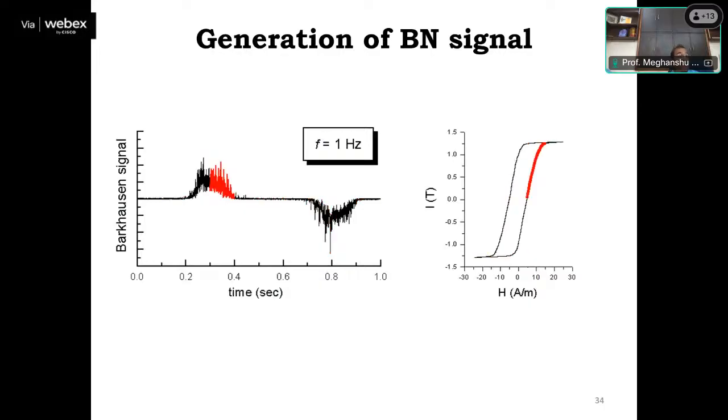This is very important because in case of the X-ray diffraction technique, we have seen that we are able to see the quality of only 10 micron depth of the workpiece thickness. Here, in case of Barkhausen noise signal, we can change the magnetizing frequency as per our requirement, so we can change the depth of penetration as per our wish.